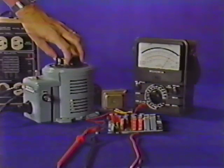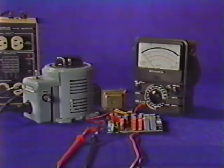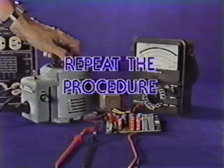Gradually increase the variac's output. Generally, the load circuit which is at fault will begin to overheat and fail before the fuse blows. After the problem in the load circuit has been repaired, it is good practice to repeat the variac test to make sure that other components are not also defective.